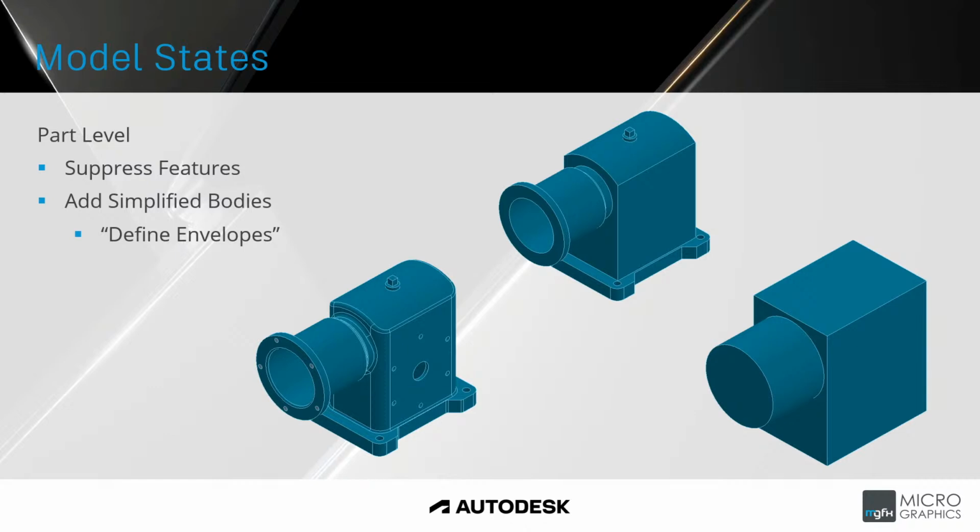Just as a quick definition for model states, if I want to expand that a little bit for those of you watching that have not worked with model states, it essentially allows you to create configurable parts. You can have 4 or 5 different states, and in each state you have different features active, maybe different parameters that have changed from state to state. But in this case, what we're looking at is using model states to simplify the components down.